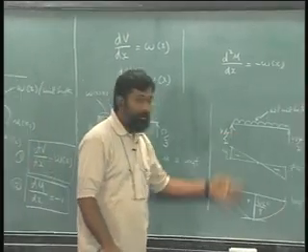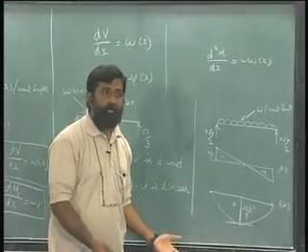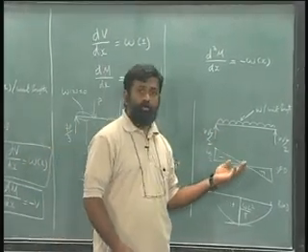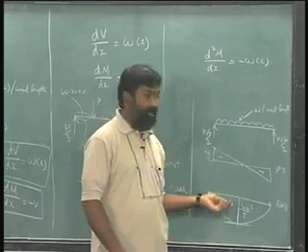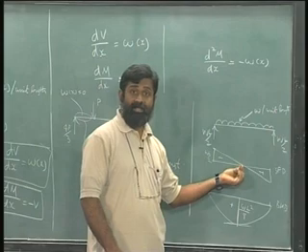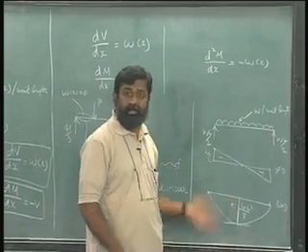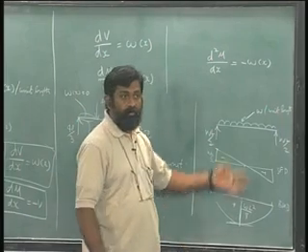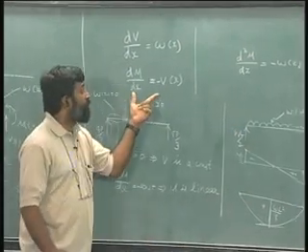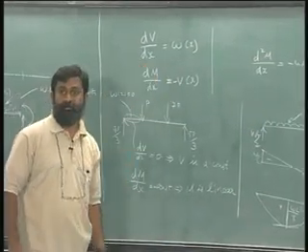Okay. So, there are some conclusions that you can make. For example, in a beam where I want to find out where the maximum bending moment would occur, it is enough to draw the shear force diagram, find out where zeros are existing in shear force, and that will immediately tell me where I should be finding out the bending moments. Okay. So, that is the advantage of using these expressions.